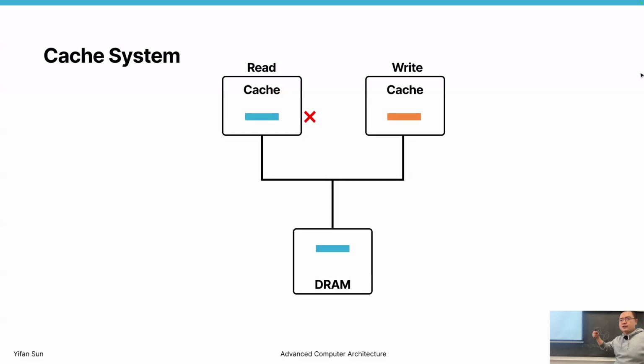On B side, we start to write, incrementing A until 42. So it's okay that for some time A is not reading the most up-to-date data, but eventually it has to arrive at this point. If you don't have anything that can evict this data and get the newest data, then this core may get stuck. But this is not strictly a memory consistency definition.